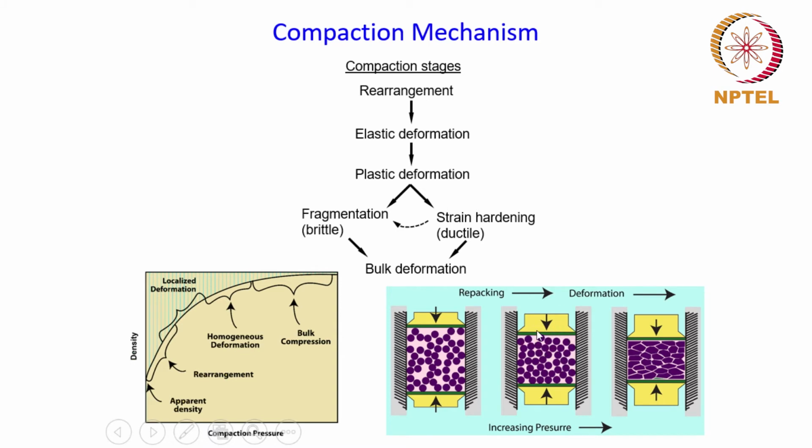And once this rearrangement happens, the deformation process will start when the powder particles will start to deform, make contact with each other, and the pores in between them will start to collapse and the powder will start to densify, right? So that is what you can see in this particular pictorial over here. So here in this direction the pressure is increasing, and with increased pressure the different kind of phenomena that we have described here you can see in terms of this kind of schematic.